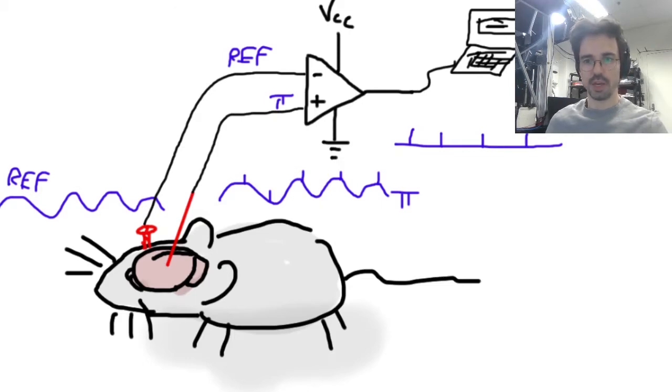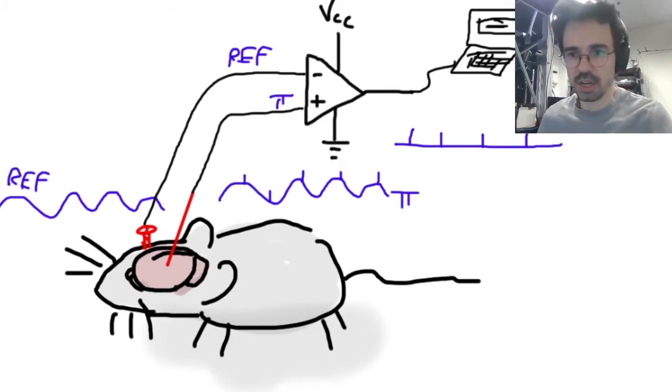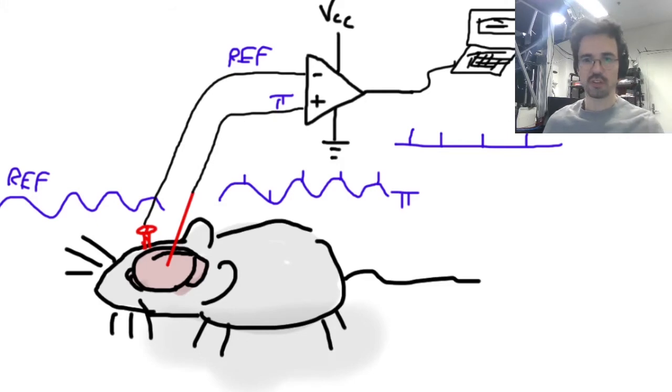That's the first problem. And so in the lecture on instrumentation amplifiers, we'll get into why an instrumentation amplifier, even though it has very good common mode rejection, cannot very easily deal with potential difference, right? At some point in here, the inputs need to be referenced to the outputs, which are ground referenced, so we can't have an arbitrary input range on our amplifier. In fact, most amplifiers have a relatively small input range, so if you had something like that, you would saturate the amplifier like crazy. So that's the first reason why this might not be a good situation.